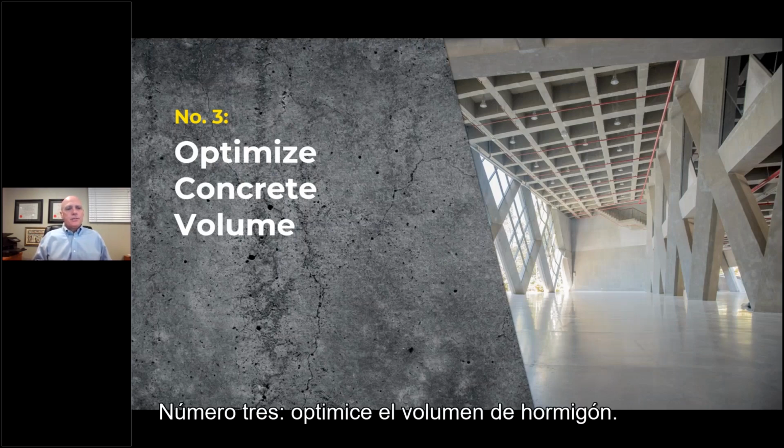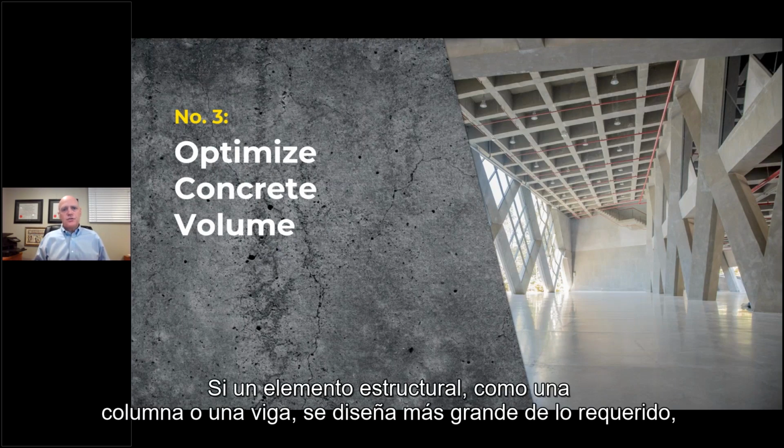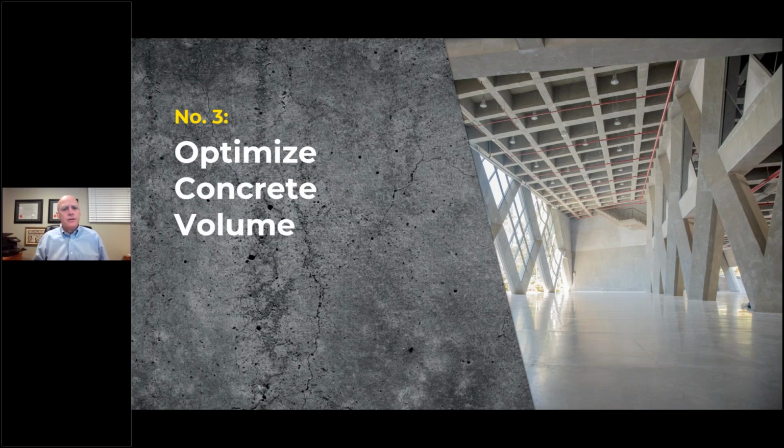Number 3, optimize concrete volume. This strategy is just about employing good design practices. If a structural element, such as a column or beam, is designed larger than required, then excessive concrete is being used, which increases embodied carbon.